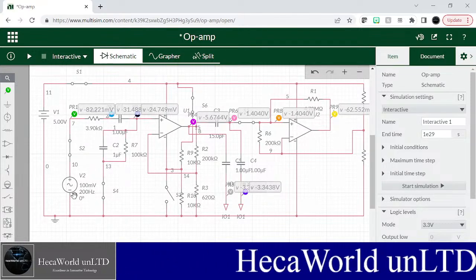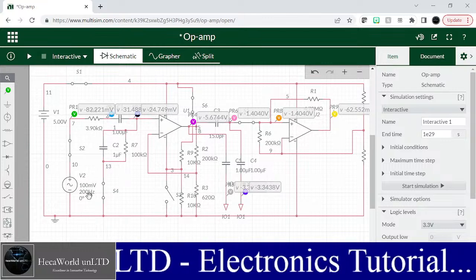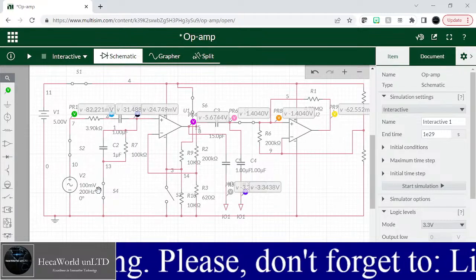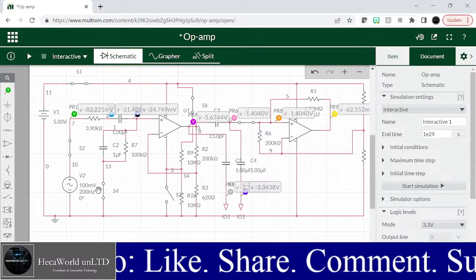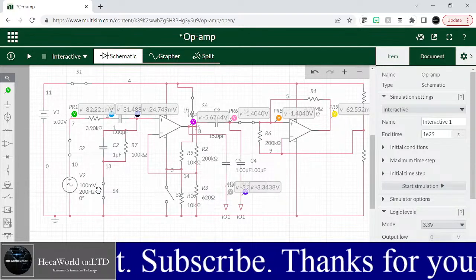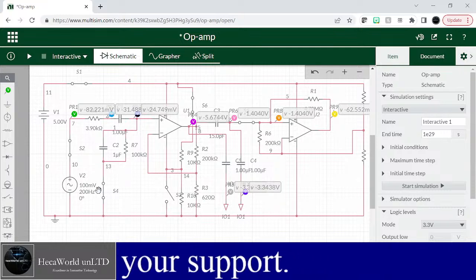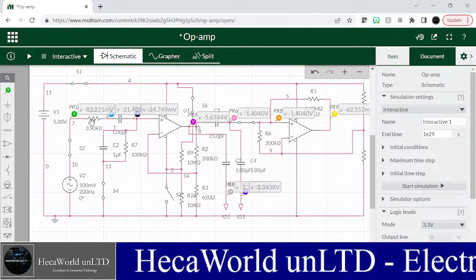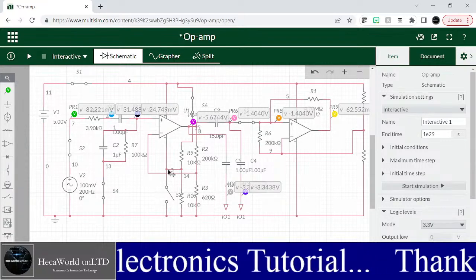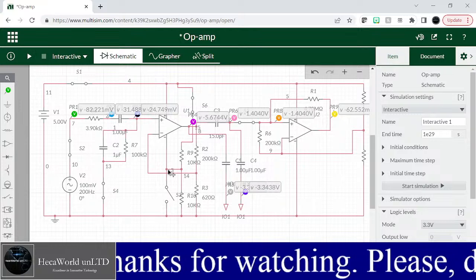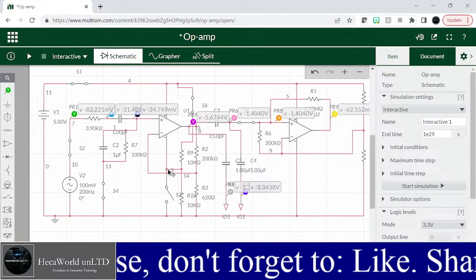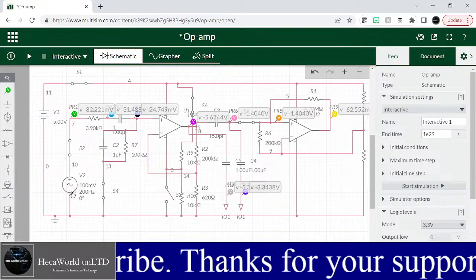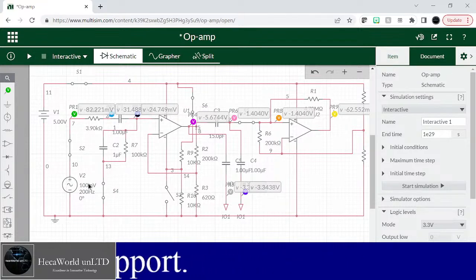So here I'm replacing the RF front end with a 100 millivolt AC generator at 200 hertz. This 200 hertz is to represent the audio signal from a human being or from any source. So any audio signal from this source, and then the rest of the components are maintained as is from the circuit, the R433 receiver.